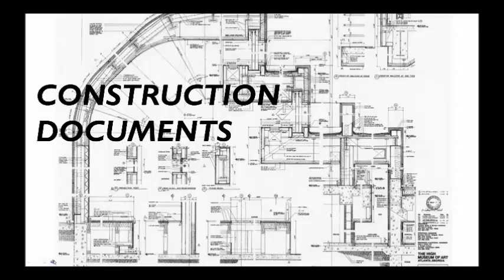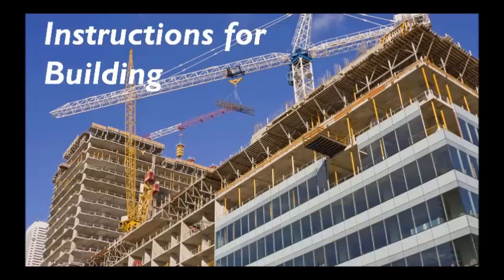And part of how you become aware of what you should show in construction documents is almost going through the building mentally and saying, okay, what order is this going to be built? So maybe they're going to start with the foundation, and you say, okay, well, do we have all of the drawings and models necessary to show someone how to build the foundation? Are there enough instructions for how to build the foundation? And that's not just the drawings, that might include the specifications, that written document listing all the materials. That's all a critical piece and part of creating these building instructions.